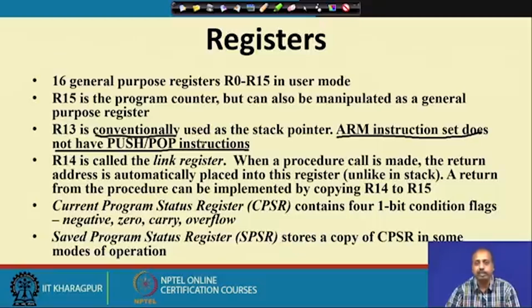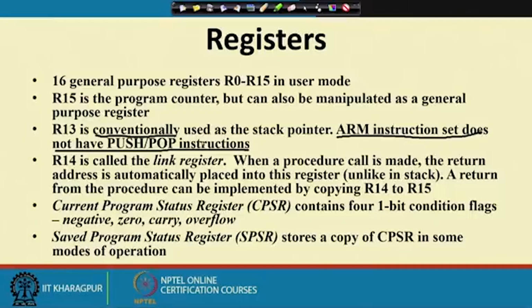It may be written in a flat fashion, so the entire code is a single routine with no subprogram. In that case I do not need any stack, so why should I have the burden of a stack? If I need a stack, I can define it in my own way, which we will see later, but by default ARM does not have any stack pointer.